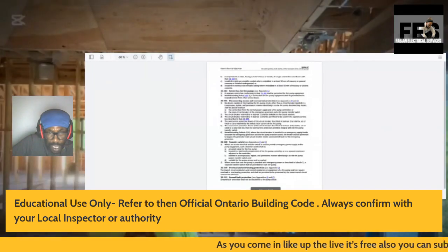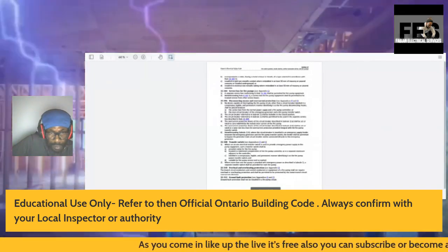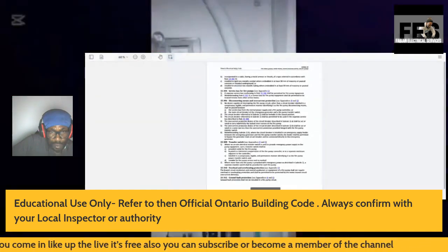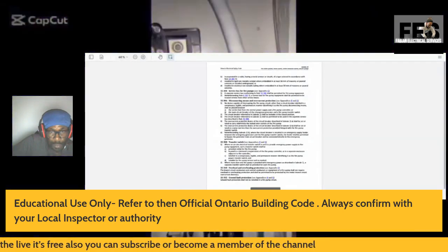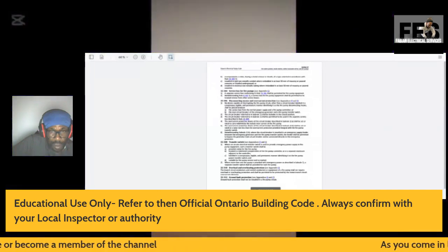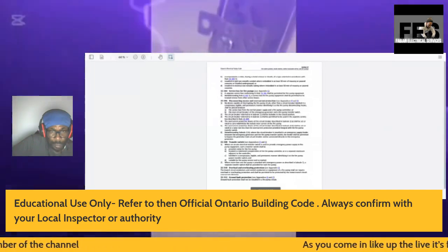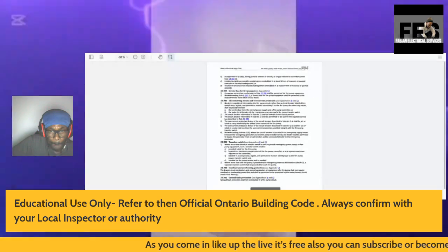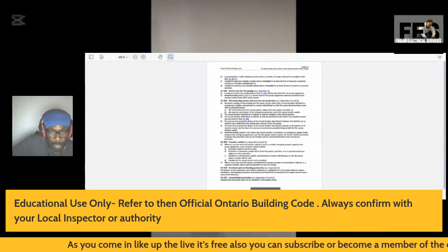Fire pump disconnecting means shall be placed between the service box from the normal power supply and a fire pump controller, or the main circuit breaker of the emergency generator and a fire pump transfer switch.